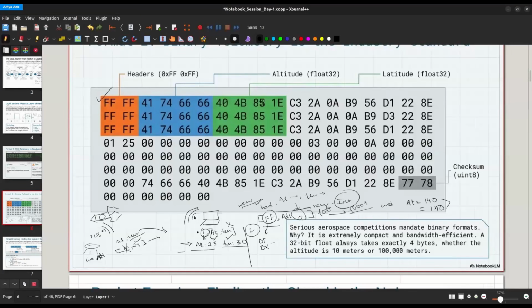That means after the launch, when you have the data, you can analyze, okay, this is 140, this is 140. The time has changed, but the value did not. Basically, we had a packet loss of altitude at this index. See how smart that is? With the simple change of just adding a header and a footer, if the value starts with a header, it's a new string. If you recognize a footer, that means the string ended.